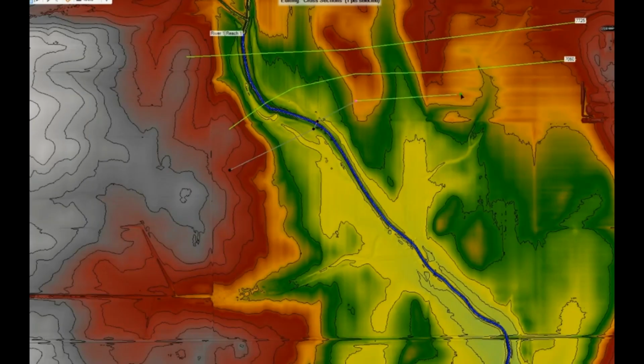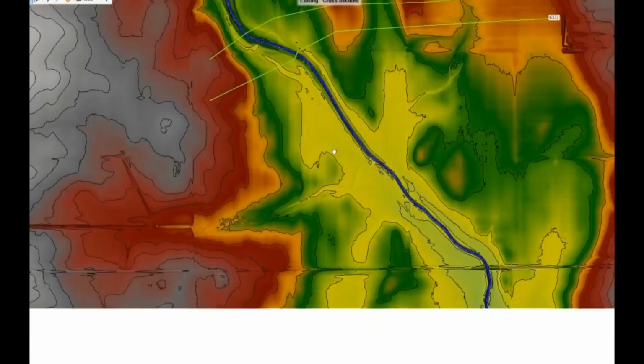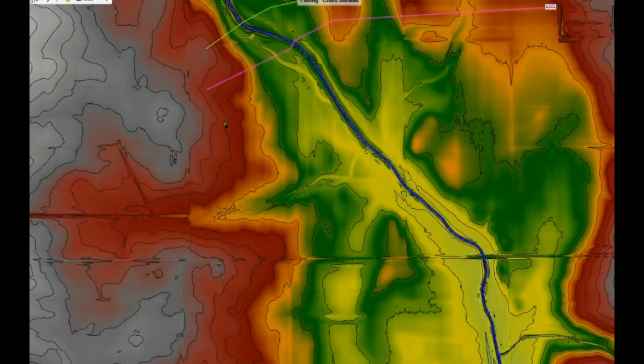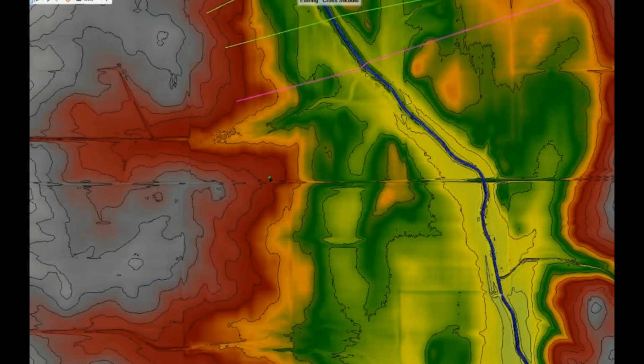Now let's add reality to the picture. Rivers bend, they widen, narrow, split, and reconnect. Keeping every cross section truly perpendicular to the local flow direction becomes slow, repetitive, and honestly exhausting, especially when accuracy matters. And accuracy does matter. A slightly rotated cross section can change hydraulic properties, affect conveyance, and quietly degrade your results without warning.